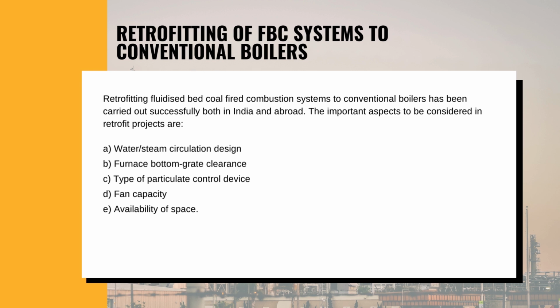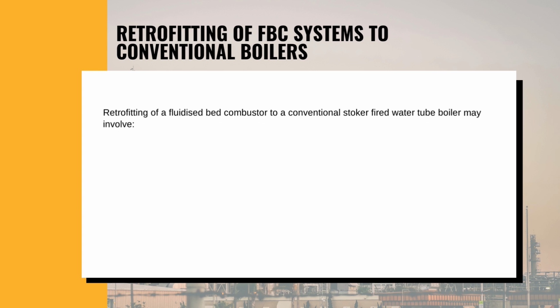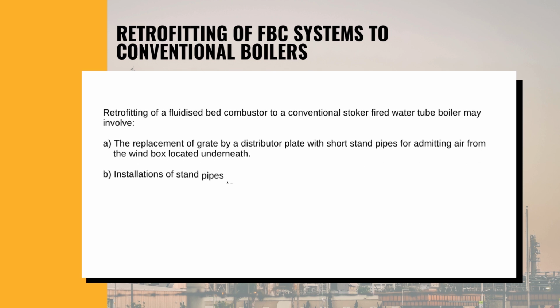The important aspects to be considered in retrofitting projects are: number 1, water or steam circulation design; number 2, furnace bottom grate clearance; number 3, type of particulate control device; fourth, fan capacity; and the last, fifth, availability of space.